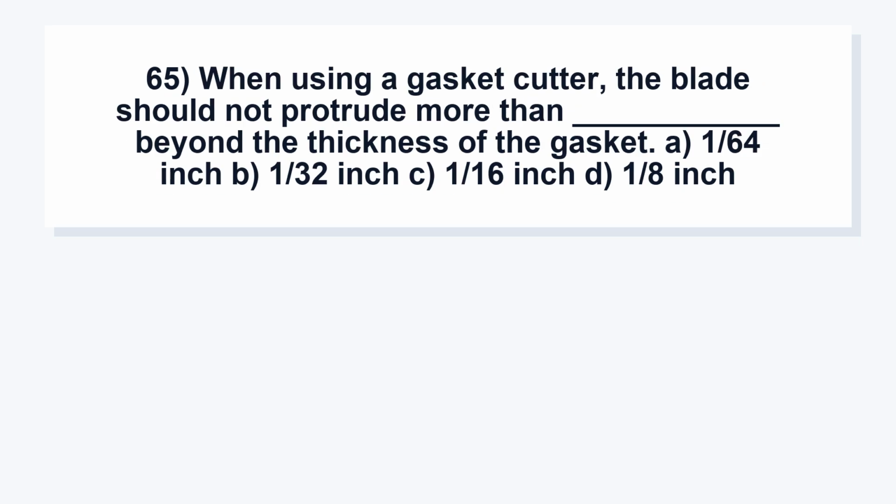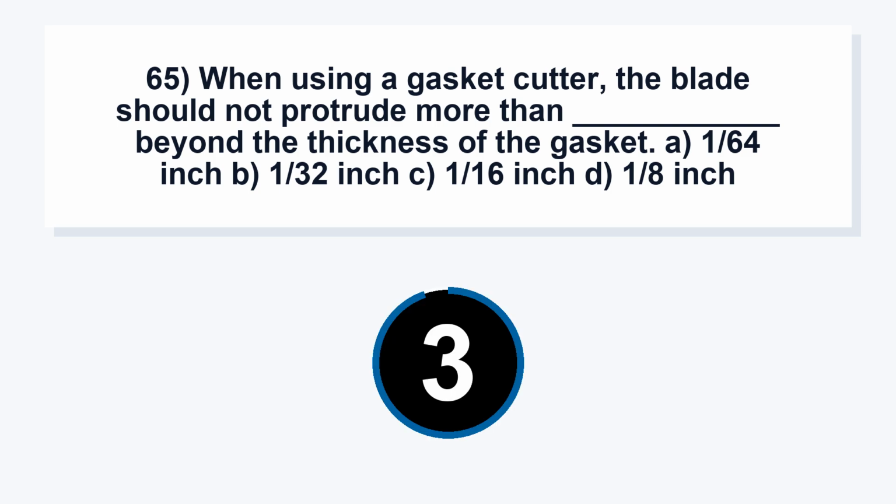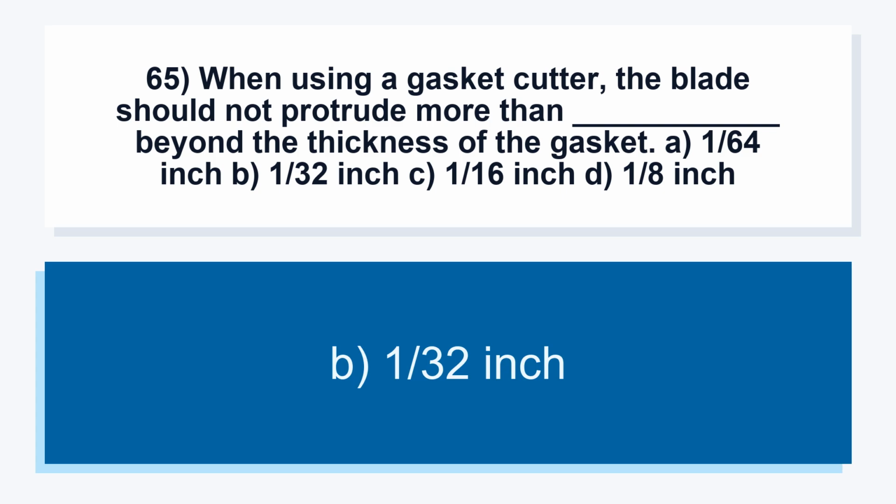65. When using a gasket cutter, the blade should not protrude more than blank beyond the thickness of the gasket. A. 1/64 inch. B. 1/32 inch. C. 1/16 inch. D. 1/8 inch. B. 1/32 inch.